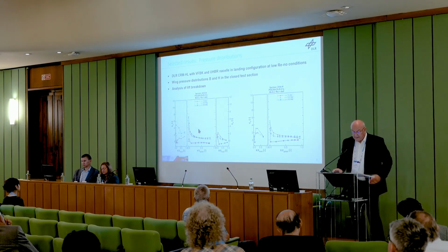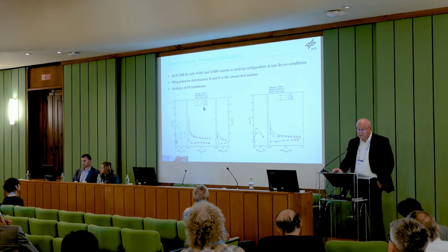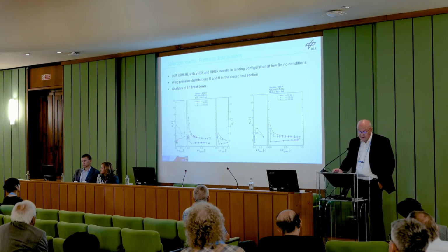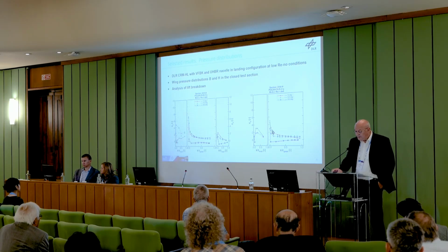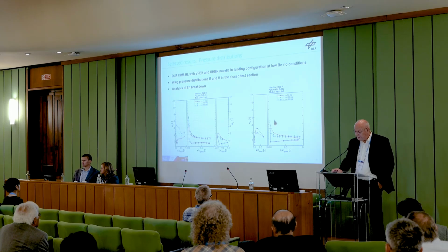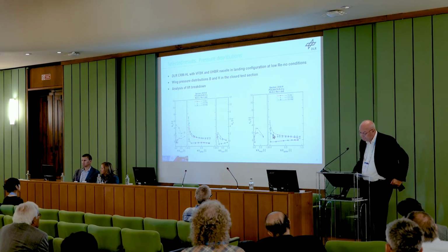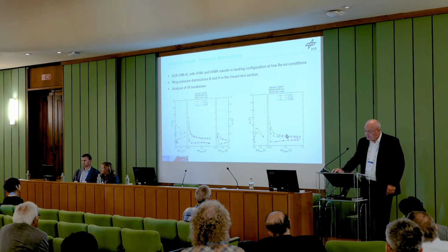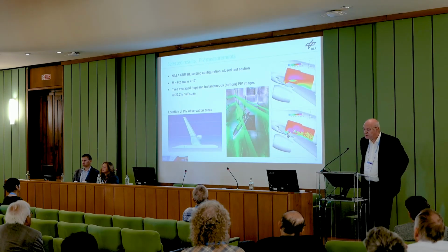Looking at the angles of attack, we go up from 8 degrees to 15 to 19 beyond CLmax. And if you look at that, you see that basically the inboard section is okay for that. And that the lift degradation or the lift breakdown is triggered by the outboard section here on the slats. The blue curve is the highest angle of attack compared to the other one, and you see the drop. And you also see the separation on the fixed wing. All right, that was the example for the pressure sections.